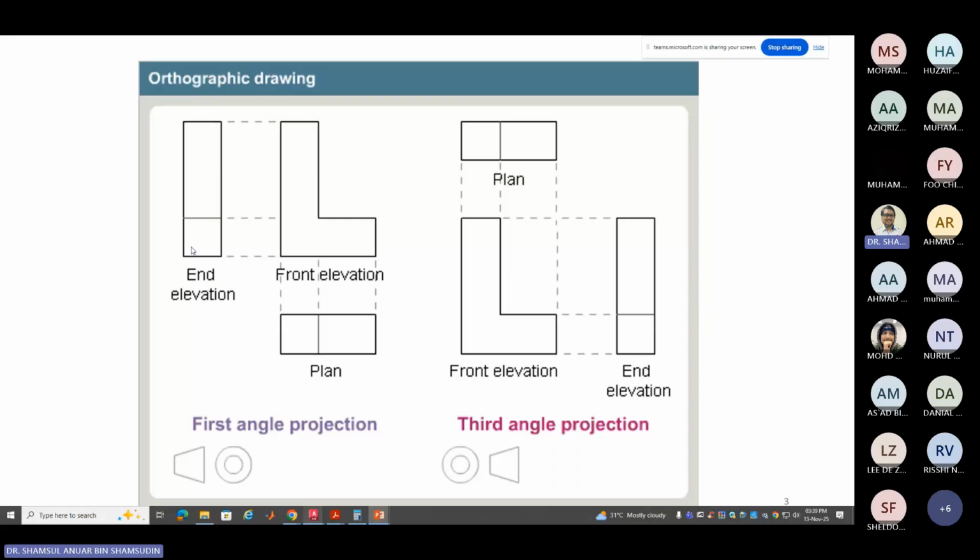Whereas in the third angle projection, if you look and see this thing from the right of the front view, you draw it on the right of the front view. So if you look at something from the top and you see this, you draw it on the top of, or above, the front view. So in a lot of senses, third angle is much better. It's making more sense than first angle. What do you think about this thing? Do you like first angle or third angle?